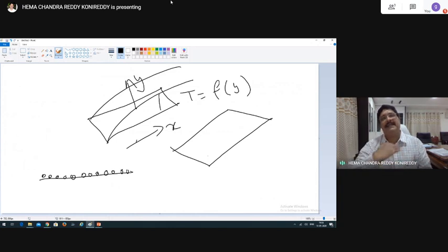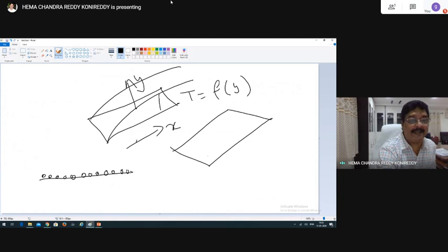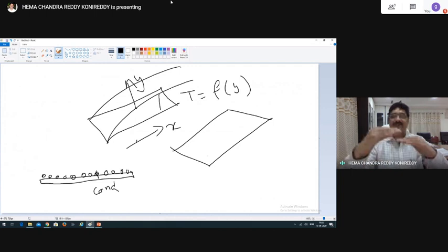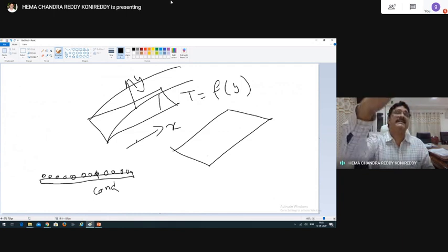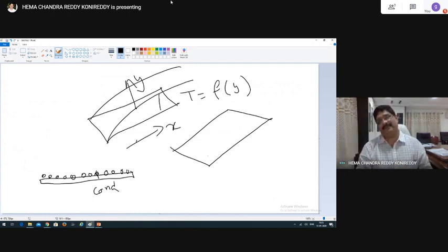Now, the heat transfer from the plate, I've told you already, initially happens to the fluid only by conduction heat transfer. Since the first layer of molecules are establishing a physical contact with the plate, the heat transfer to the first layer of molecules is only by conduction. And whatever conduction heat transfer happens at the first layer, simultaneously upward it should be convected.